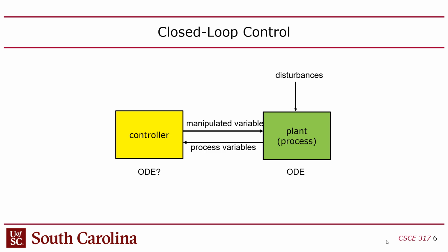And I've heard that there are louver designs for greenhouses that actually open and shut using thermal expansion of the louver itself. So as the louver gets hotter, the metal expands and it opens. And as it gets colder, the metal contracts and it closes. So that's a controller, but it's not a computer-based controller. It's a continuous controller, it's not discrete. But most controllers are discrete because they're CPUs that are running.